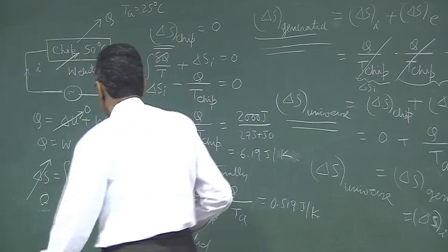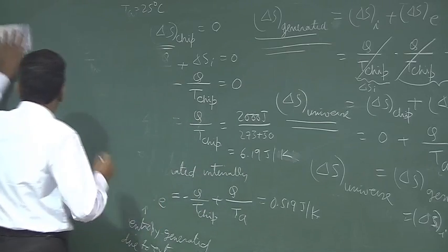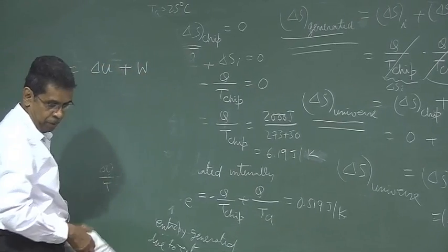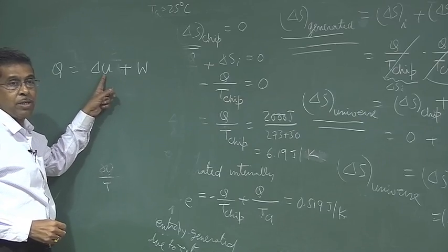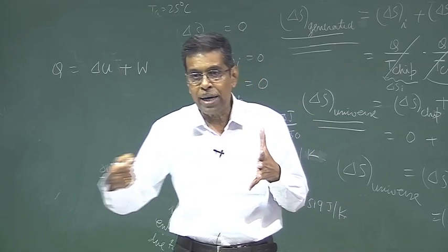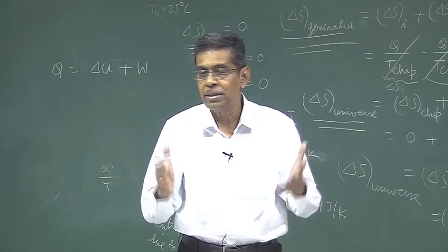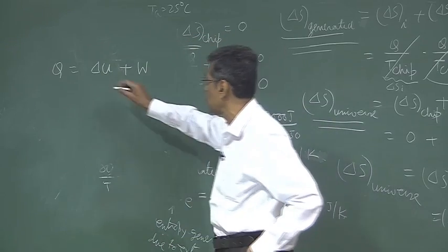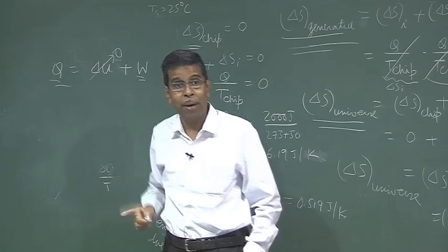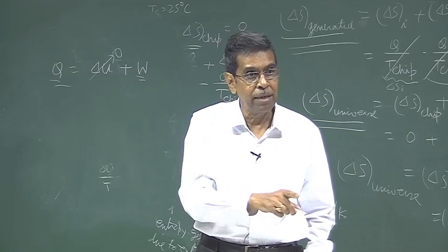Now, after that, I told you certain tidbit concepts of thermodynamics, which many people do not have. Q is equal to delta U plus W in any single process. Now, there may be a process where delta U is 0. For example, if you take an ideal gas and supply heat and get work in a way that the temperature remains constant, then since the ideal gas internal energy is a function of temperature, the internal energy remains constant. So there may be a process where delta U is 0, and Q can be converted into W by the same amount, but it cannot be converted into W continuously in a cyclic process. That is the restriction by the second law, the Kelvin-Planck statement.